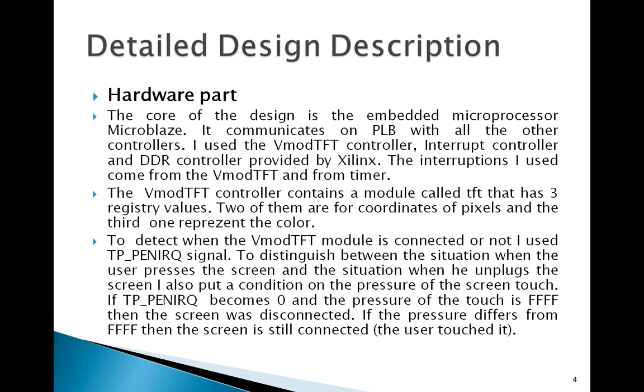To detect when the VmodTFT module is connected or not, I analyze the output signals of the VmodTFT module listed in the VmodTFT reference manual. These signals are TP bus busy, TP out, and TP PENIRQ. I use the TP PENIRQ signal. This signal is an interrupt, active low, at the moment when the user presses the screen, but its behavior is the same when the module is disconnected.